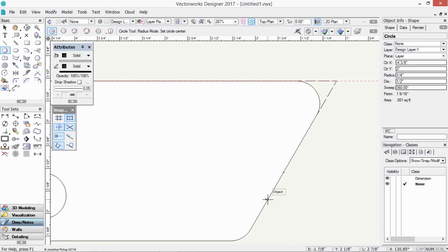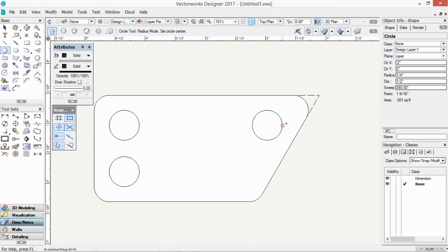What about this edge? Touch the edge, hit the T key, and you can see my dashed line running through it. So come away half an inch, there's an offset there. Follow that offset all the way up till you get the other one as well. So it's offset, offset, both of them. Click, 0.25, enter once, enter again, so that's a half inch circle there.